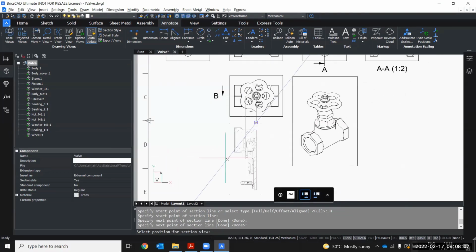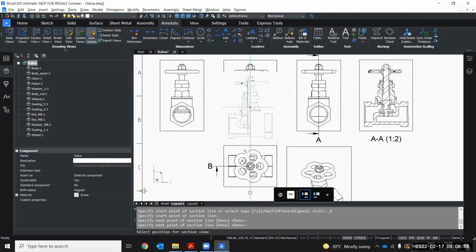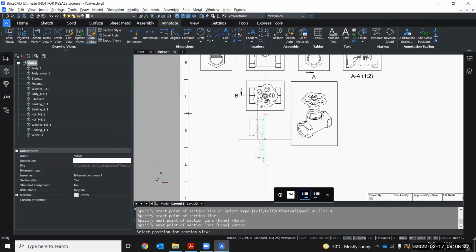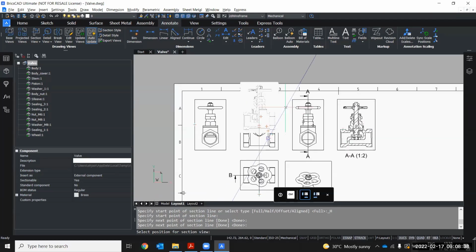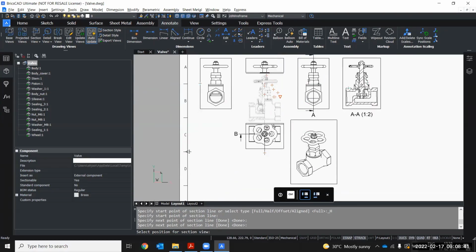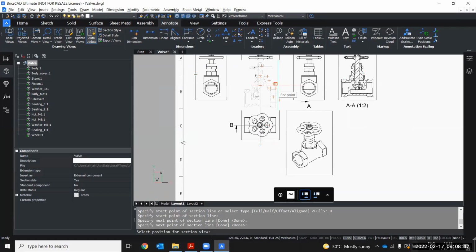If you see, if I drag it downwards, it gives me the quarter section view of the section lines that I just placed. And if I drag it upwards, it would give me the rest of the 3/4 view that is there in that particular view. Okay, so this is something that you can choose from. So you want the quarter section or the 3/4 section of the view. So it would be selecting the 3/4 section of the view. But as you can see, I cannot drag it rightwards or in the left direction because it's constrained with the view here. Okay, so the alignment is still there.